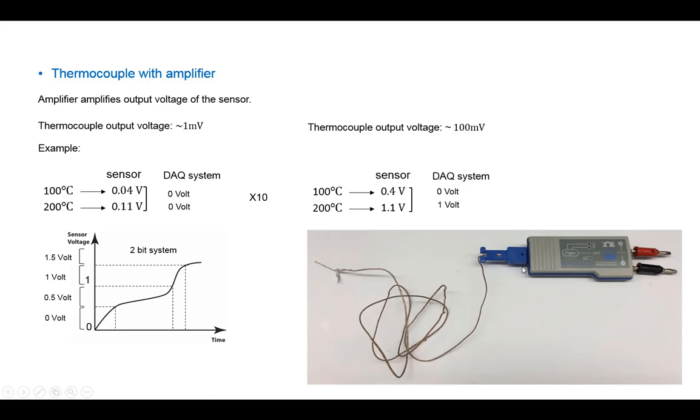We see how by increasing the sensitivity, or amplifying the output voltage of the thermocouple, we now have a better measurement of the data. In the earlier case, the system could not distinguish between two different temperatures and just stored both of them as one value. But here our system has a better accuracy of measurement. Two different temperatures also give two different voltages at the output.